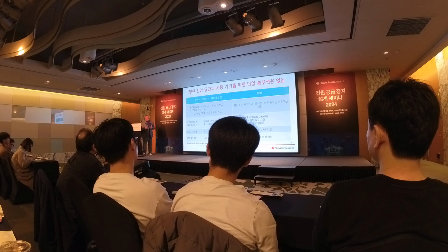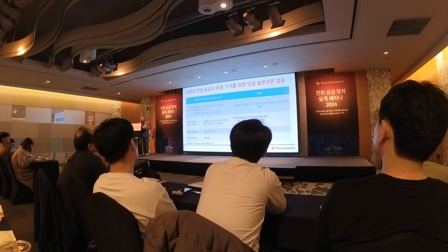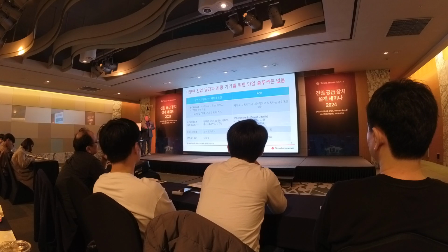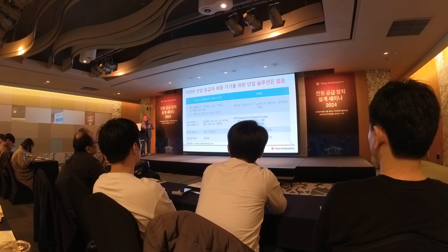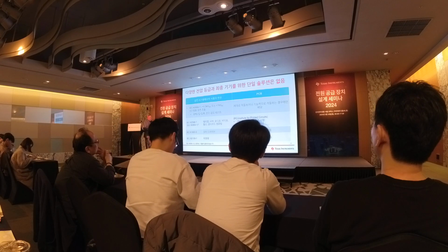Okay, if we look at the PCB then, again, a lot of IEC standards cover proper PCB creepage, clearance, those types of things. But an important one to look at here is the IPC. This is the Institute for Printed Circuits. So general requirements are given in IPC 2221.